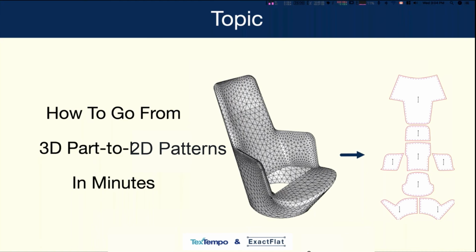So as we approach no strain, that creates a pattern with a perimeter length that is pretty much identical to the 3D model. Depending on the type of geometry you're working with, if you have double curvature, it's pretty much impossible to avoid stretch or strain or even a bit of sag every now and then. So there might be some fluctuations, but the important thing is that sewn edges, two edges that sew together, are typically preserved, and the error between the length of one sewn edge compared to its neighbor is usually very small. Usually the error that we experience is on the order of maybe 1 or 2 millimeters. So the notches that we generate are extremely close together. The amount of error in there is very small.